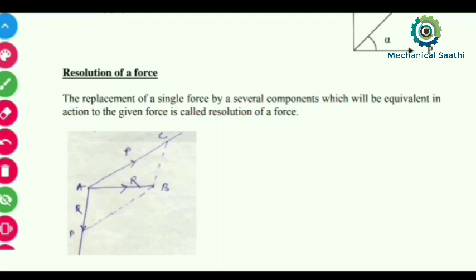So how can we do that? Let this be R, which is given, and this is the resultant force. Resultant will be given, and we can calculate the components of these two forces. If we take along the x-axis or y-axis, we can find that out. If we draw any parallelogram, then these two sides will represent the components of this resultant.